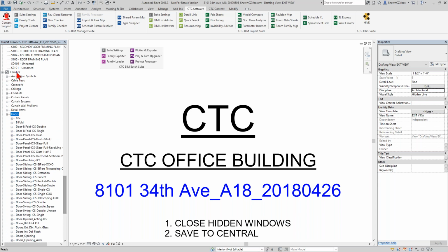I do have the ability to go up to families and save all families out in one big step. The problem with this, and this is definitely an opinion-based thing, is that this save is really frustrating because it takes every single family and saves it all out to one unorganized directory. So annotation symbols are sitting next to doors or detail items, all sitting together, and sometimes it can be a little tricky to identify what's what and how I'm supposed to be handling that content. And in most cases, that's way more than I need.